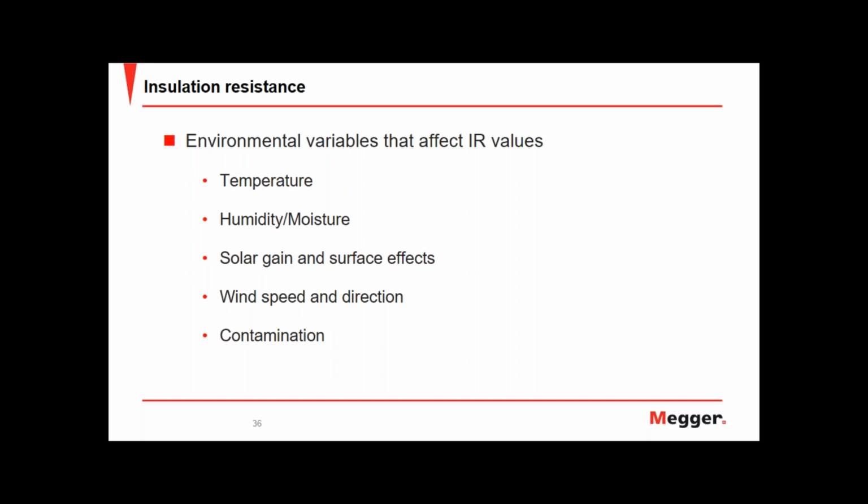But first, a little bit of background. In assets such as coil windings found in motors or on HV bushings, the surface of the insulation presents quite a large area on which contamination can land and build. Contamination can occur naturally due to airborne pollutants such as dust. It could be salt from the air in a salty environment, where we are here in Dover. We're very close to the sea. It could be diesel particulates from vehicles. These all add up to contaminate the surface of an asset.